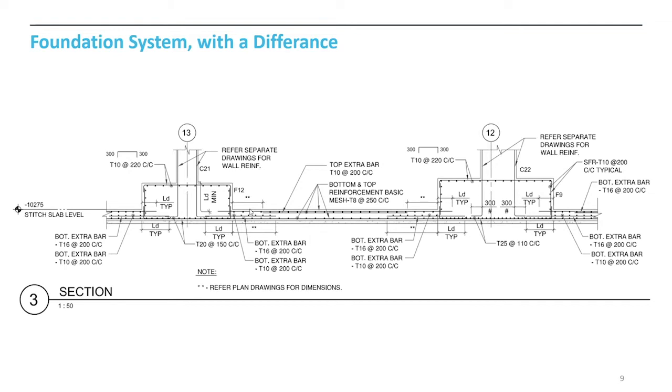And a benefit I can think of is that you can have uniform waterproofing below this, and when you level this up to the top of the foundation, that acts as a counterweight and gives benefit to resist the vertical water pressure.